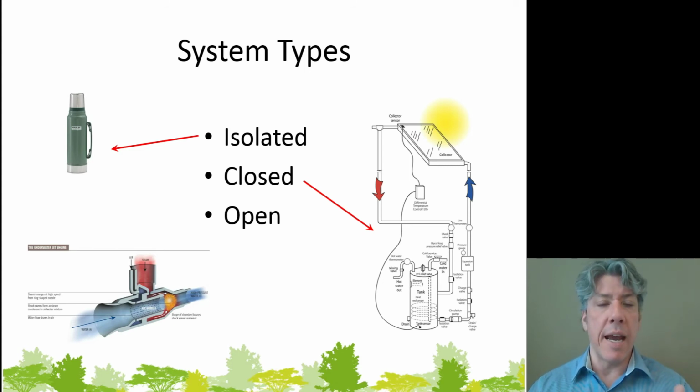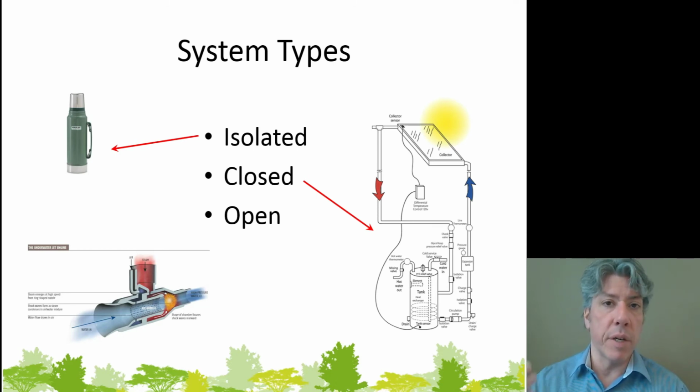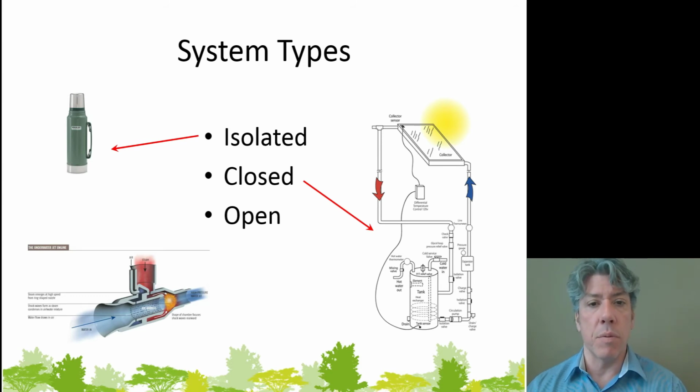So it would not work to have this directly exchange thermal energy with the water in the tank. In other words, you couldn't just pour it into the tank. You'd need a separate coil in the tank that this water runs through, and this schematic doesn't show that very well, but that's the way it would be set up in the real world. So if we imagine the water in antifreeze that runs through the collector and then through the heat exchanger in the tank, that water would be a closed system where energy crosses the system boundary, obviously, because solar energy goes into it and hopefully comes back out, right, at the tank to heat your water, but there's no mass that crosses the system boundary.